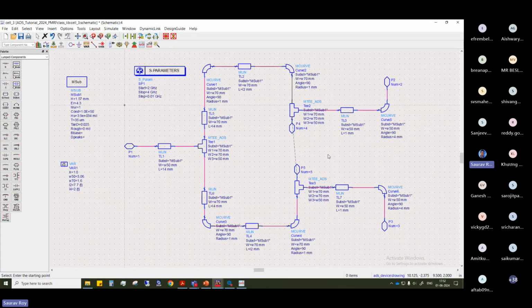Okay. So first you can do a normal simulation with the resistance itself. Then, if you remember, I did a tuning also. Those tunings, you have to remember, are possible only in the schematic, as far as I know. So first you do the complete simulation in the schematic. You tune the results so that you get very good results. And then you move to layout.